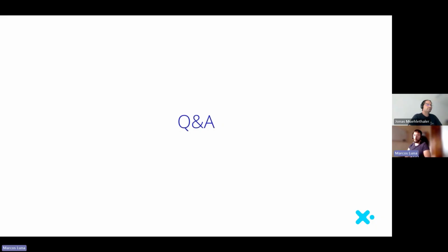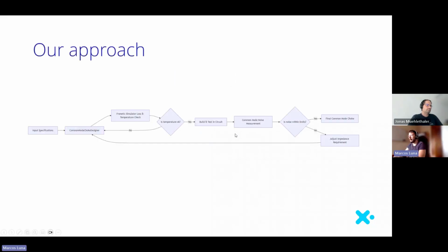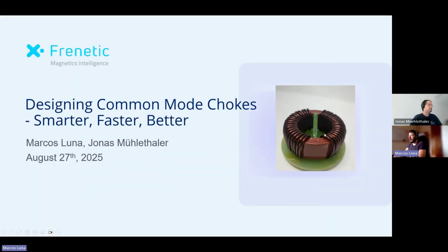To meet the creepage and clearance distance, if you see this component here, there is a plastic part, which is more for the mechanical side than the design side. It needs to be fitted together with the core, acting as a barrier to keep the creepage and clearance distance in this direction.